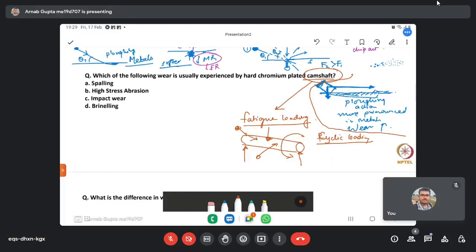Yes, yes. So yeah, in abrasion you see that it is grazing on the surface, and as a result of that, wear is happening. And the load which is acting on the particle will be higher than in case of low stress abrasion. As a result, some plastic deformation is happening, and then microcracks are generating, and as a result, wear is happening.